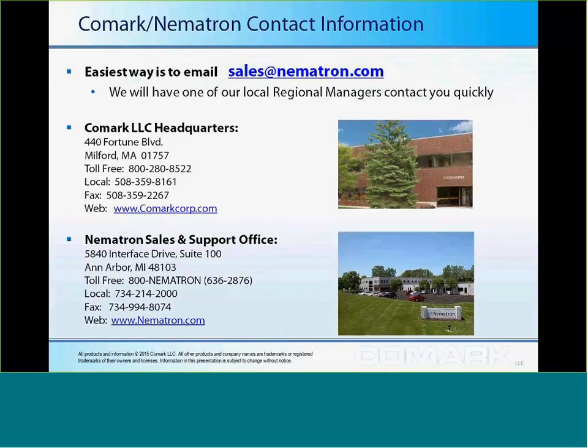Ralph, you touched a few times on Class 1 Division 1, Class 1 Division 2, and ATEX approval. I know from both of our backgrounds that's dealing with hazardous locations. Do you want to touch on what environments those types of approvals might be required? Class 1 Division 2 is a possibility of a hazardous condition. And when you're in chemical processing plants, oil and gas, some food actually, there's a possibility of a condition that could cause explosive material to be in contact.